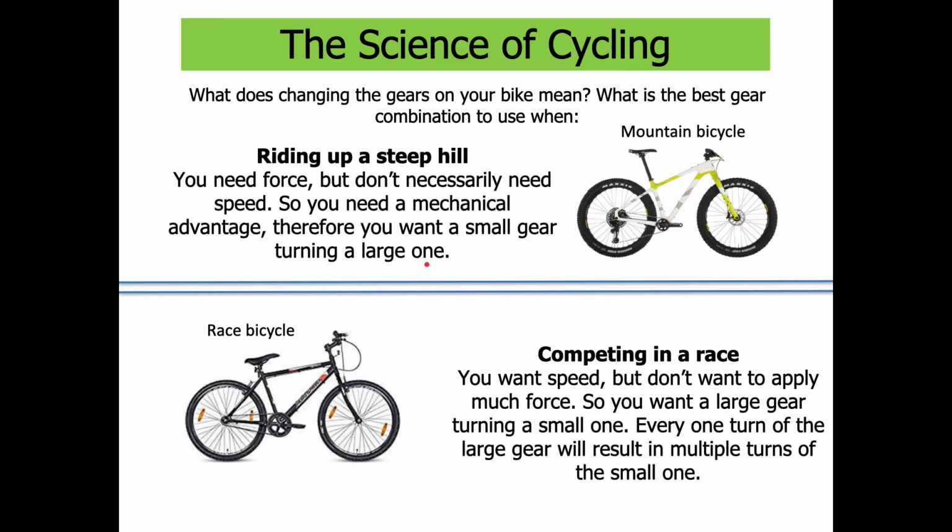But if you're competing in a race and you need speed, then you need the larger gear turning the smaller one. So it's very, very important that you understand and can distinguish between the two ways to manipulate the gears. If you want speed, your larger one will be the driver and your smaller one will be the driven. If you want force, then your smaller one will be the driver and your larger one will be the driven.